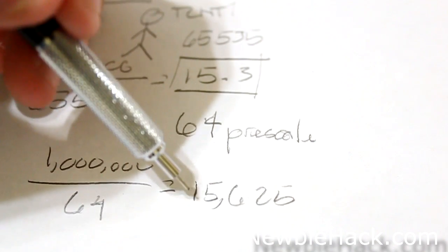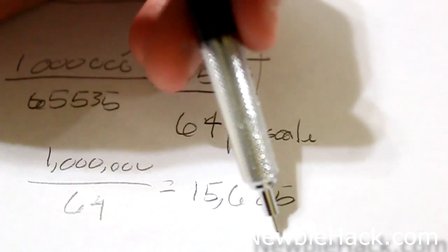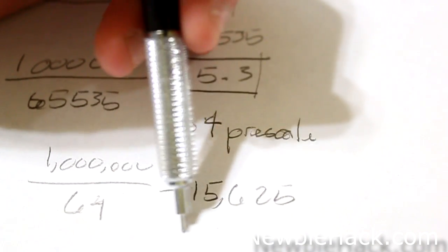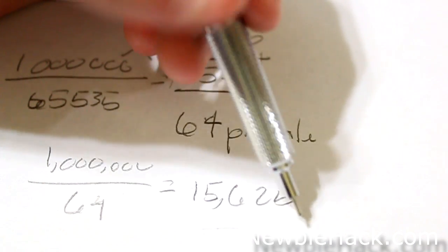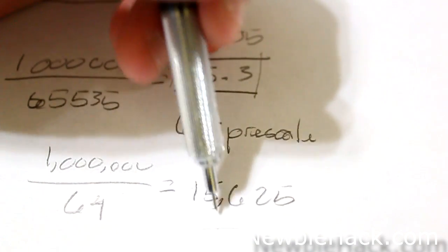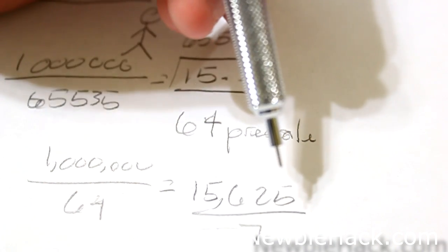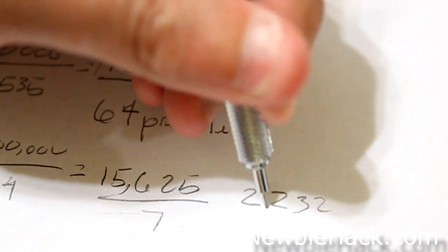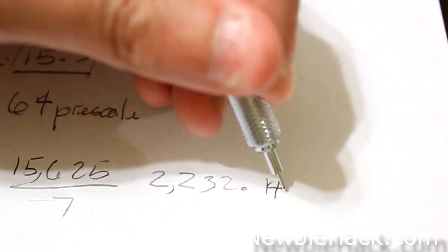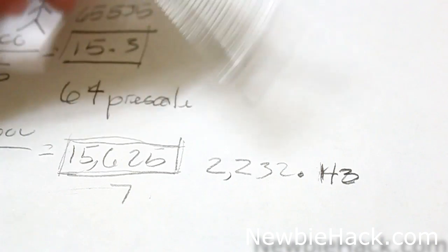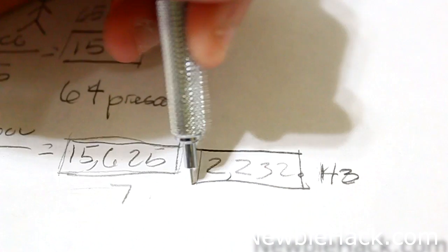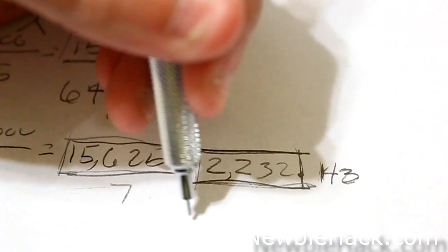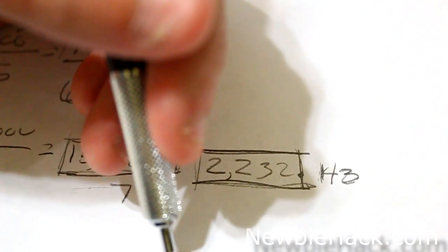But we also want to do the LED chasing for every 1/7 of a second, and then on port D we want to be able to chase it every second. So we need to take this number and divide it by 7. It looks like we have 2,232.142 or 143 actually. So we're just going to go ahead and use the number 2232, and every time we have the 7 LEDs on port B lit up or chased, we will move the port D LED.